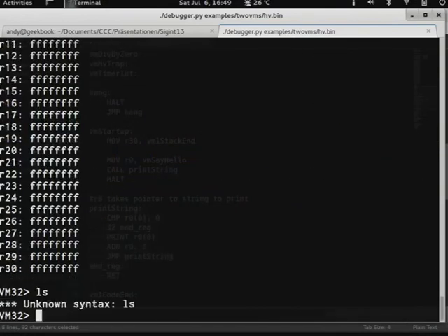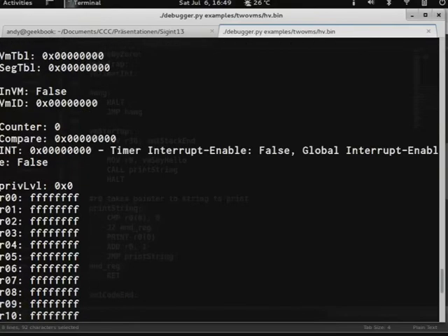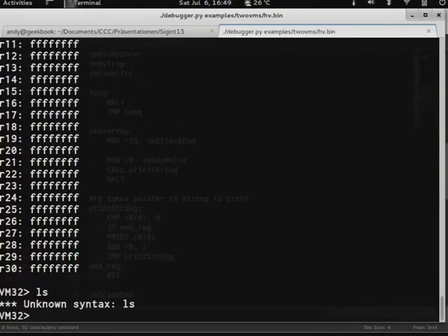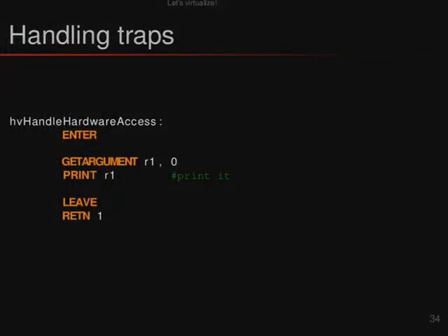Oh, I forgot to explain why the registers are actually in memory. It makes the context switch much easier, because if I have them in memory, I can reload the complete register set by just switching the register segment. If I switch the register segment to memory with a different base address, then all the registers are basically reloaded with different values. So for a context switch between the VMs, I don't need to use different moves or pushes to the stack for all the registers. I can just switch the memory segment where the registers are aliased to, and I have a different set of registers.